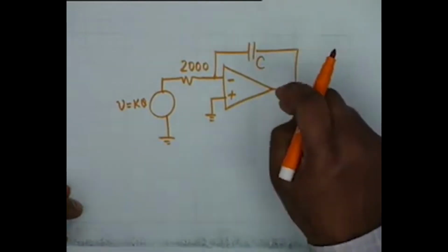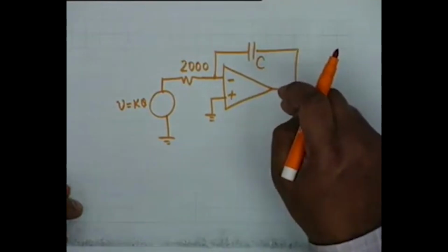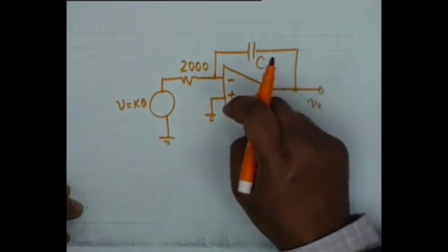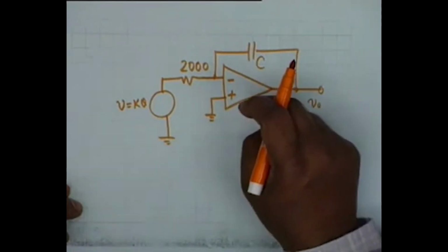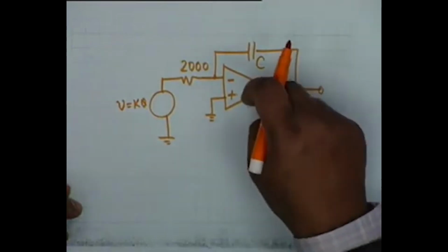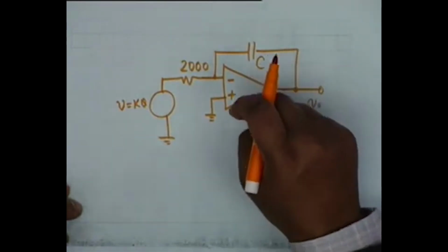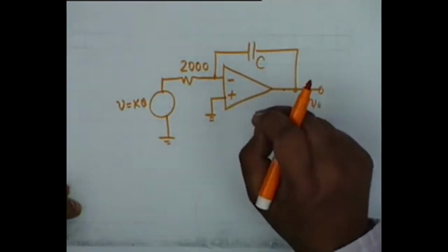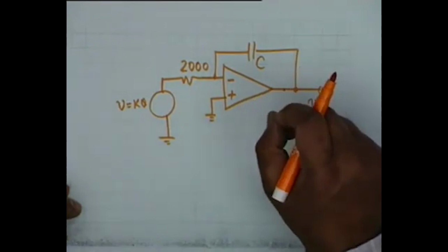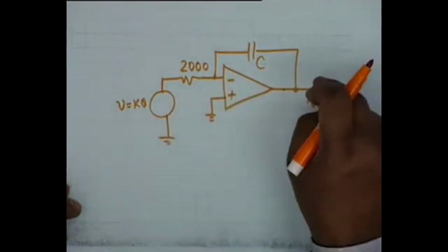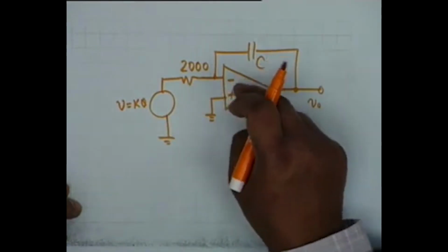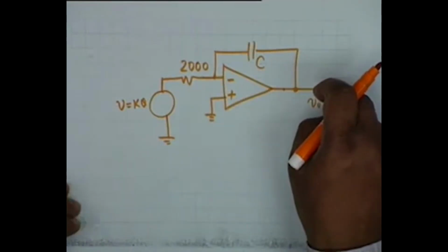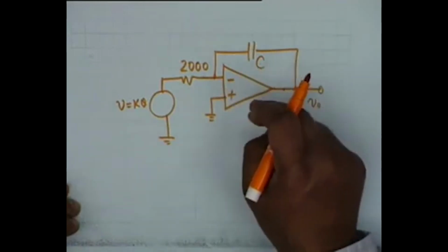For operation of an operational amplifier, negative feedback is a must, and therefore we make a preferential treatment of the inverting and non-inverting terminals. In most applications the non-inverting terminal is not touched; preferably it is connected to ground. We do all operations with the inverting terminal because anything connected from the inverting terminal to the output causes negative feedback, and therefore it stabilizes the gain.